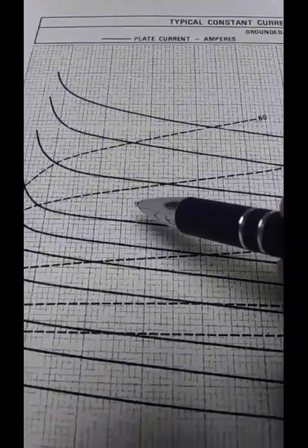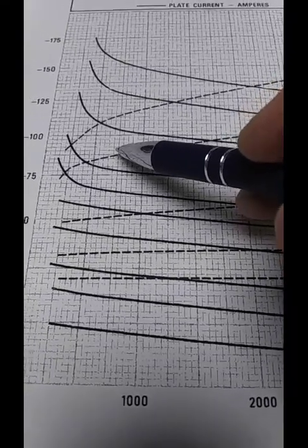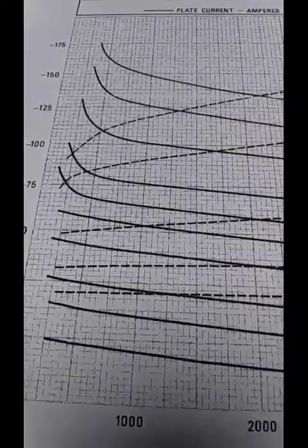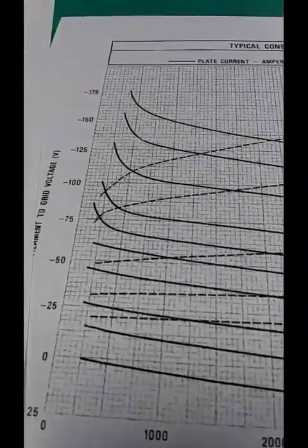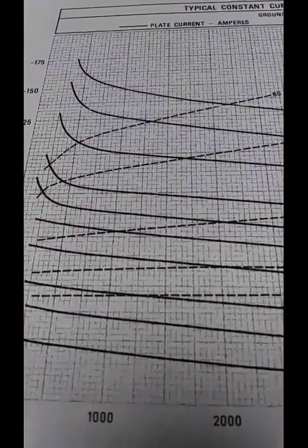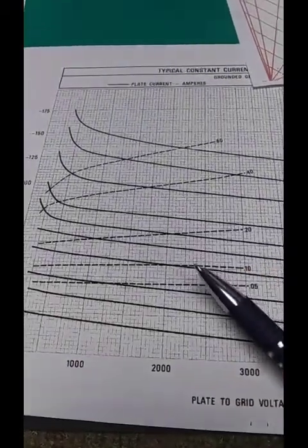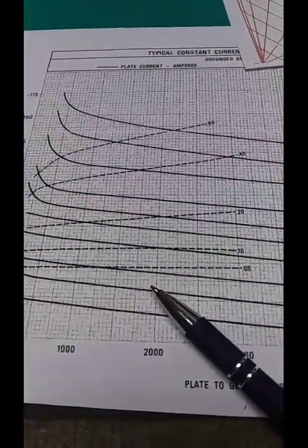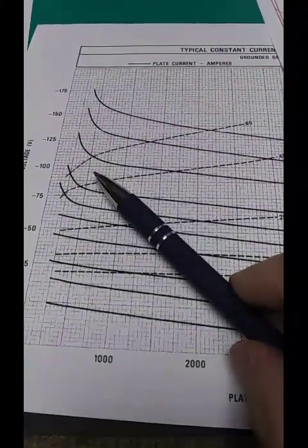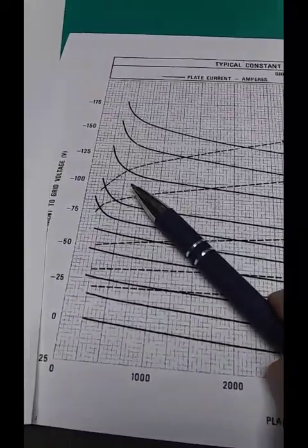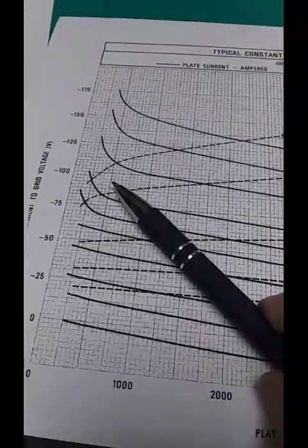So over here, somewhere over here, we're going to have to mark a dot that represents 1.2 amps and some minimum voltage. And realize going towards the right, the tube is conducting less, toward cutoff. Going to the left, it's conducting more, towards maximum current. So the operating line will start someplace over here, and we'll go up this way, over to intercept the maximum plate current, which will be two-thirds, right there, someplace right in here.